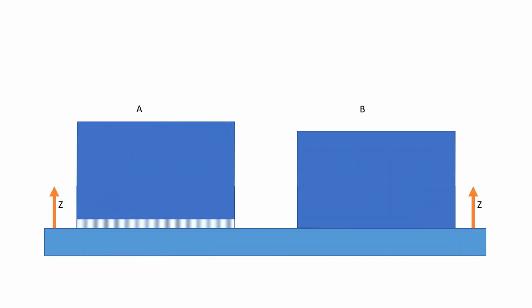The laser PBF process requires that the part be securely attached to the platform. Attachment to the platform can be done either directly, built directly on the platform, or using support structures. Support structures for LPBF processes serve several functions, including heat transfer, attachment of the part to the platform, compensating for residual stress-induced warping, and support of a piece under construction.